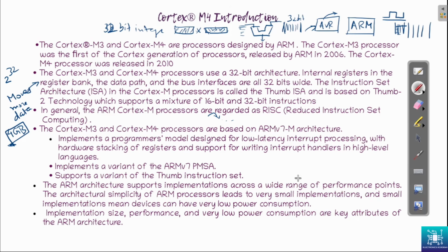Now, this is something that we will repeatedly see in the course, and we have dealt with it in depth. That is, in Cortex M, you can actually write your entire code, including startup and all the code, in high-level languages. You can write them in C with little bits and pieces of maybe assembly code in the middle somewhere. But apart from that, most of the code can be written in C. And this is a variant of the Thumb instruction set we call Thumb-2.